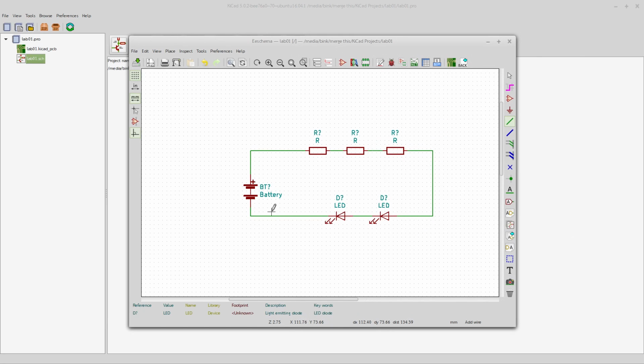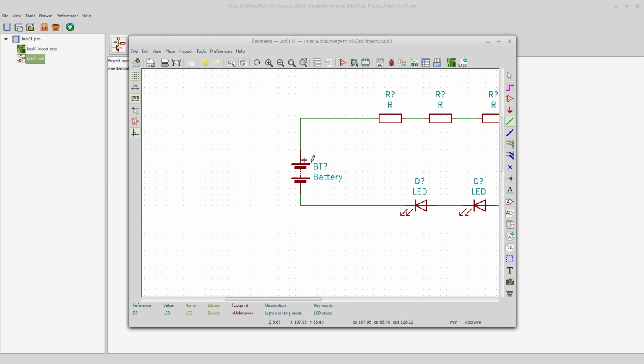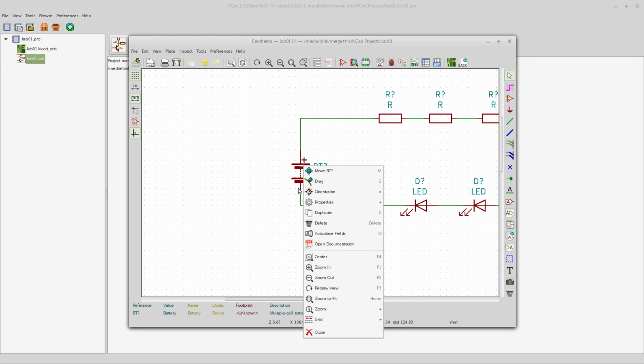Okay, so you go over here, and this being a symbol, if I click on it, well, see how I'm carrying this pencil thing to add a thing? Hit escape, and it drops it, right? So now you're free to click on something if you want without having to bring up a new component. I could right click on this, and I can have some options here, right? So you could go to properties, you could go edit value, edit reference, edit footprint, edit library.